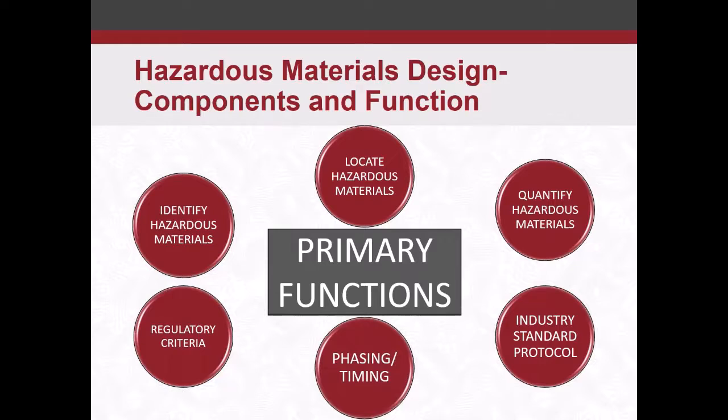And finally, phasing and timing. It's important to know how you're going to schedule your abatement. Obviously, you've got to get the abatement done before other work. But if it's a multi-phase project, can you do abatement in different phases? Do you do it all up front? So establishing that in your abatement design, letting the contractors know that certain materials come out during the first phase, certain materials come out the second phase, allows them to bid it and allows the owner to get a project that is on time, within budget, and all that good stuff.